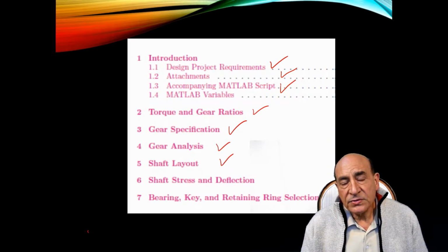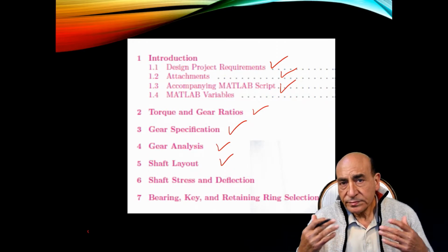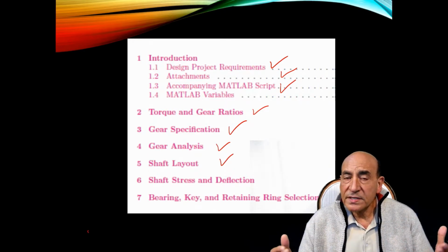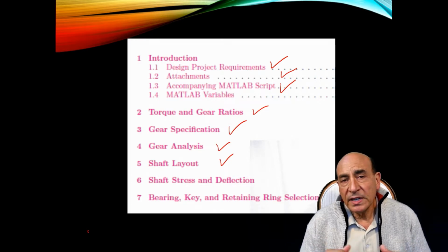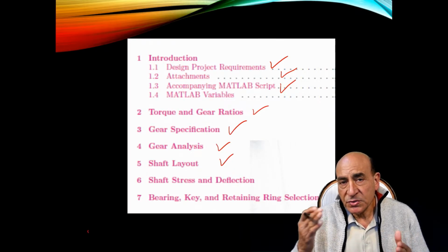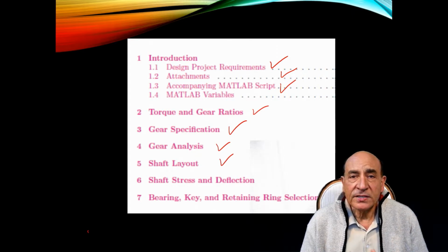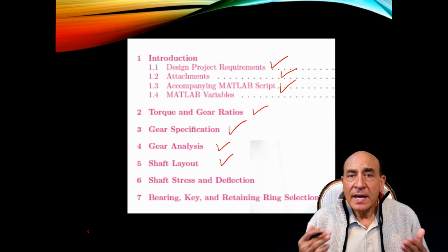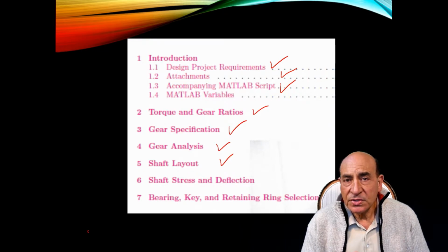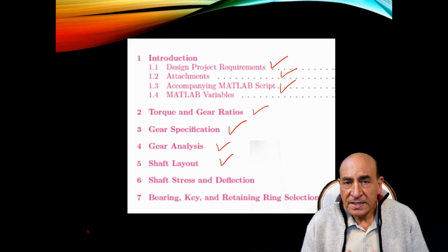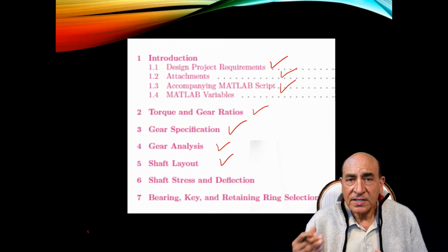And the shafts will have forces and torques and moments. So these are 3 different types of loading, and those will induce deflections and induce stresses. And the stresses will be 2 parts, one steady state and the other part is going to be fluctuating, and the fluctuating stress will induce fatigue. So a complete shaft analysis would entail deflection, stress distributions, stress concentrations, failure analysis, fatigue analysis.